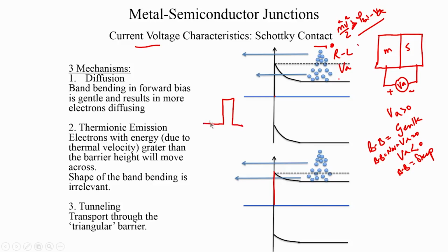When we looked at quantum mechanics, when we said particle in a box, we drew diagrams like this, the potential energy diagram looked like this, with the electron having a sinusoidal wave function here and then an exponential decay in the wave function outside the box, and that was the barrier we always discussed. But here, if you think about this band diagram, the barrier is not a rectangle. It has a straight edge on one side and this quadratic appearance on the other side.